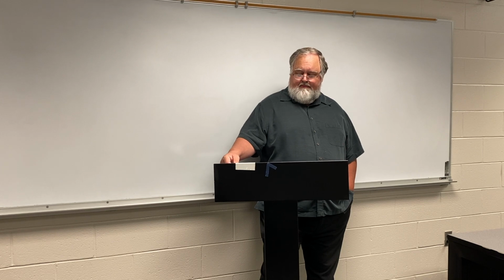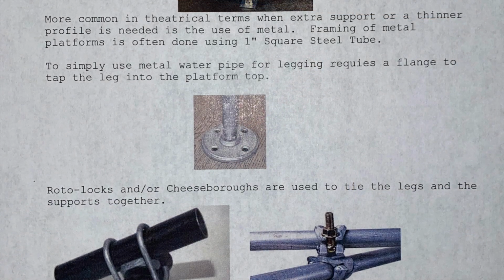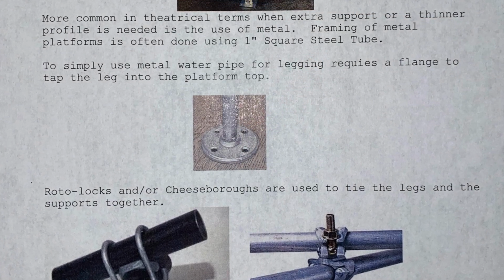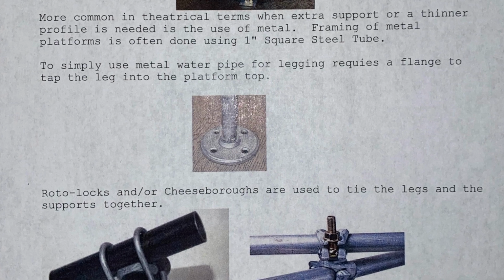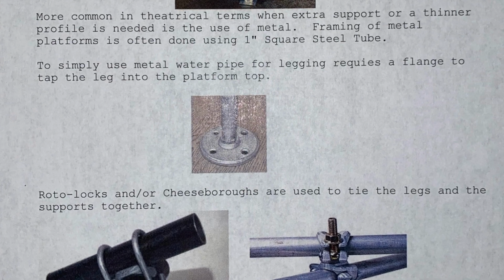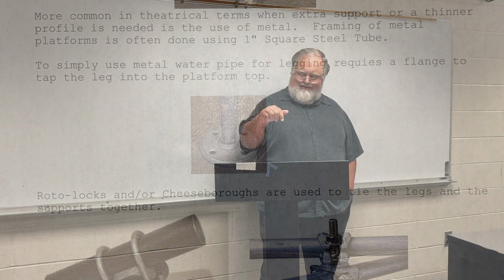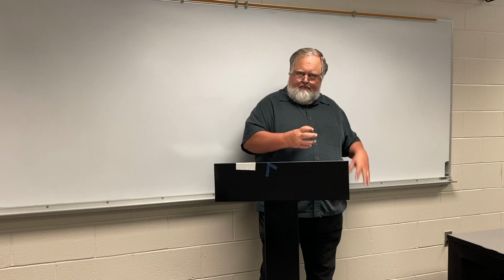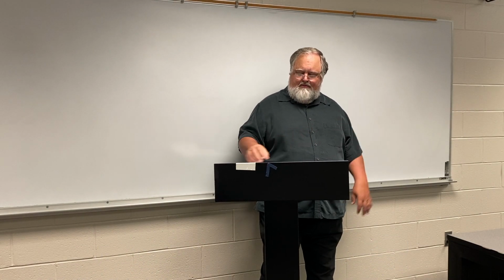And as you can see from the picture, there's sort of a circular thing, and then there's a middle piece, which is showing the other side, because there's a little bolt that screws down to add tension to that plate there, which sort of pushes the pipes apart and keeps them from sliding. But that's the way a rotolock works.